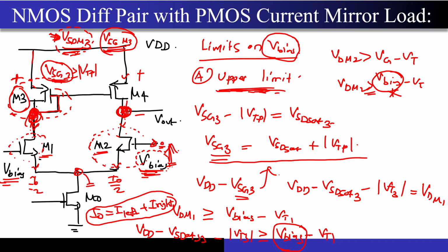Now if this voltage increases, because of channel length modulation, the current through M1 should increase because of the increase in the VDS of M1. Ideally, if the left side current increases, then the right side current has to decrease, because I am operating under the right conditions. I have placed my bias points such that all the MOSFETs are in saturation. But the increased current of M1 is getting current mirrored from M3 to M4, and again that is getting dumped into the right hand side branch. So the right side current is also increasing, and the left side current is also increasing.